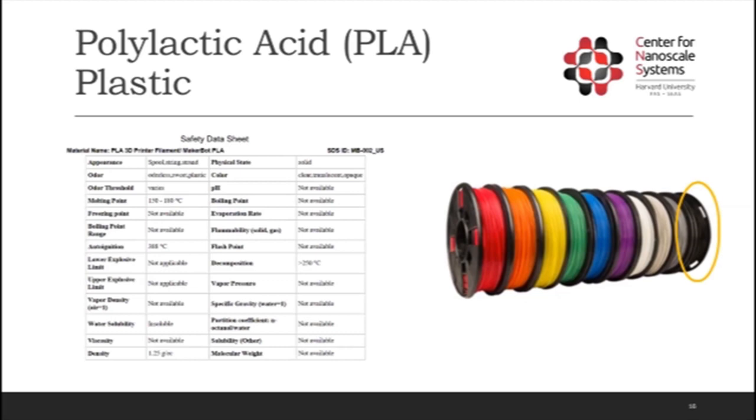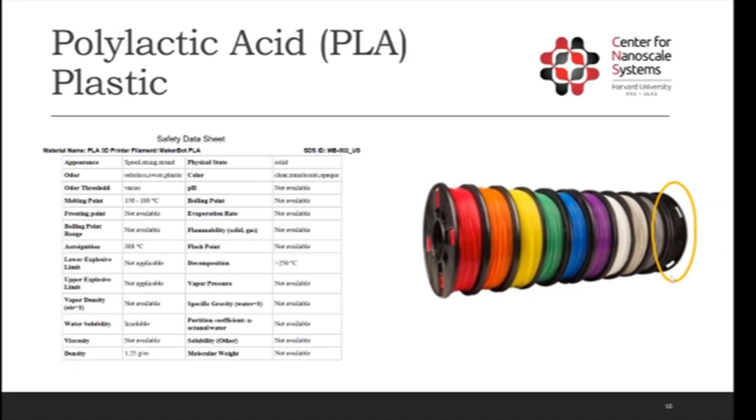because we used to provide several colors. We used to allow users to change them whenever they wanted to. And we started seeing a lot of filament clogging every time somebody printed, almost immediately when making the first layers. So by just changing to one filament, one color, we improved a lot and we don't get those clogs as much.